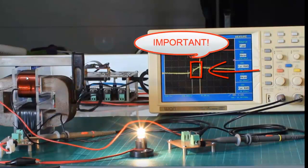But if the current can't change very quickly in the coil over here, if it's a very slow change, then we're going to have very little voltage generated. But if we have, say, a 2-turn coil with number 2 wire, so it's 2mm wire, as soon as we switch on our voltage, our coil is going to have current that rushes through really, really fast. And what will happen as a result of that current changing very quickly in that coil is we'll get a very, very high voltage on the output coils.